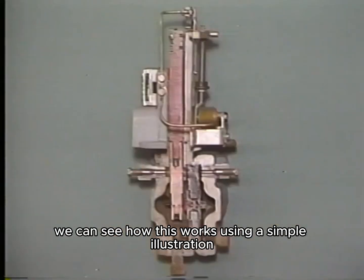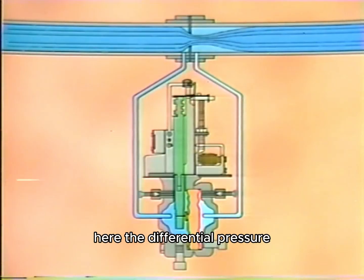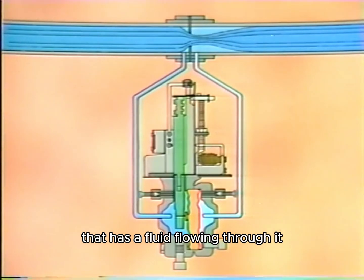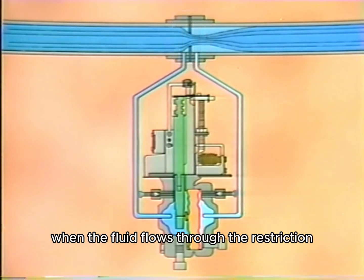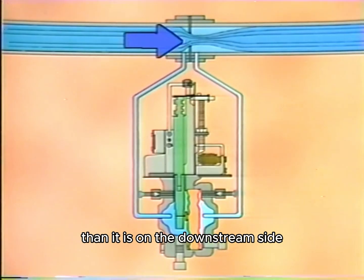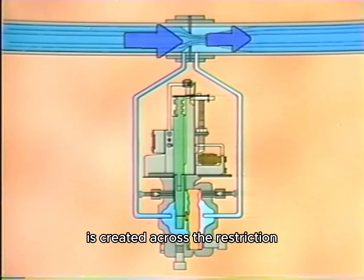We can see how this works using a simple illustration. Here, the differential pressure transmitter has been connected to a pipe that has a fluid flowing through it. Inside the pipe is a flow element or restriction. When the fluid flows through the restriction, pressure is higher on the upstream side than it is on the downstream side. A difference in pressure, or differential pressure, is created across the restriction.